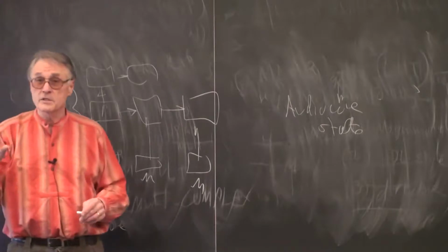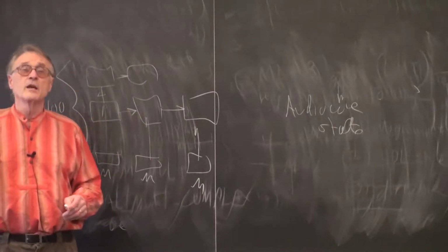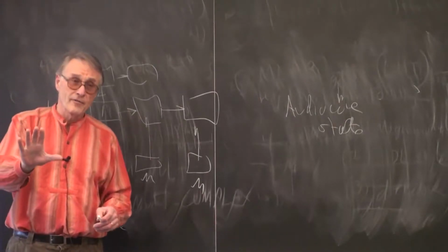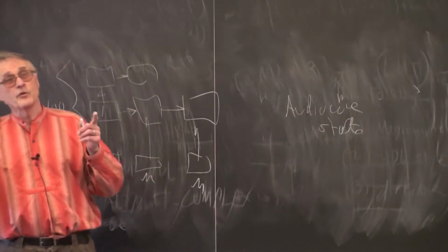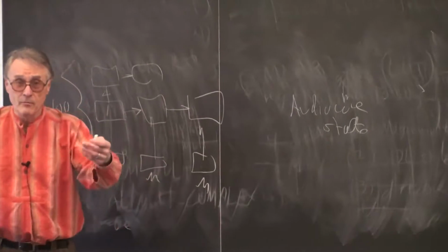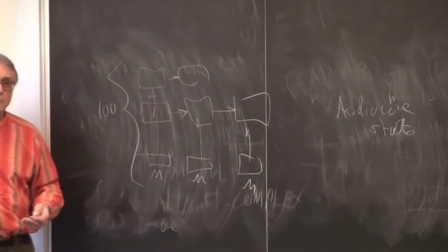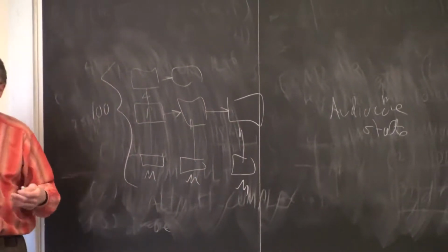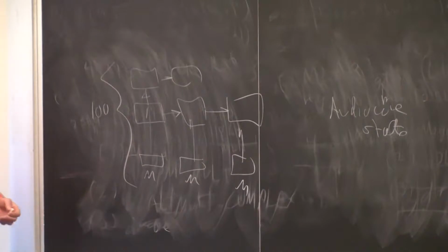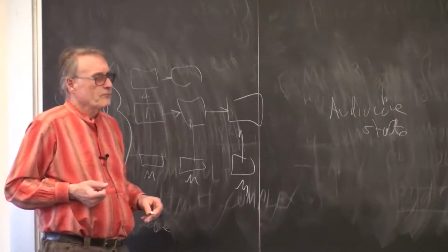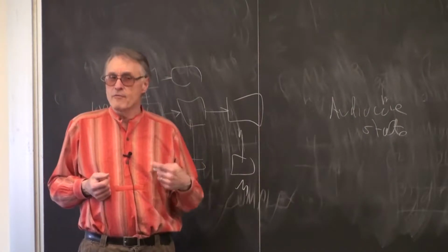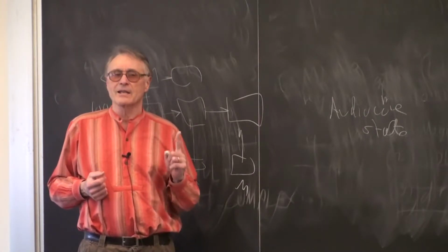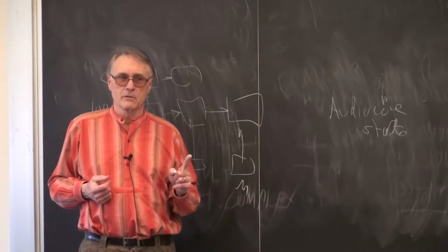But the audio core state machine has more states because you have to handle a FIFO, a dual FIFO, left channel, right channel, and you have to handle a data input to that FIFO. So there's more like 10 or 12 states rather than like 3 or 4 states. So you may want to end up simulating that, although in this case I've written that state machine almost exactly the way you're going to use it.